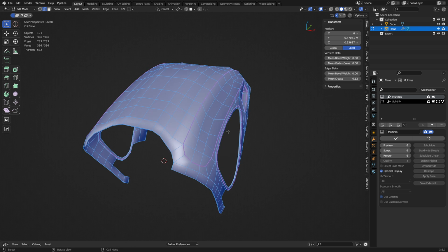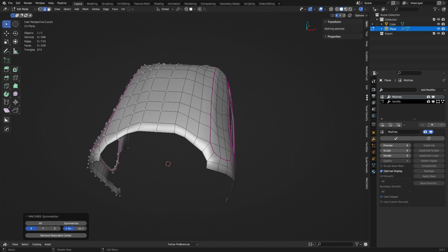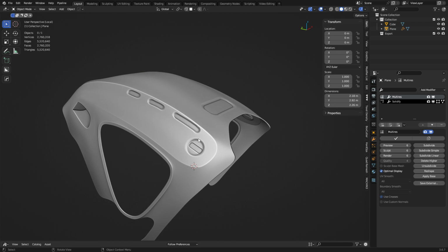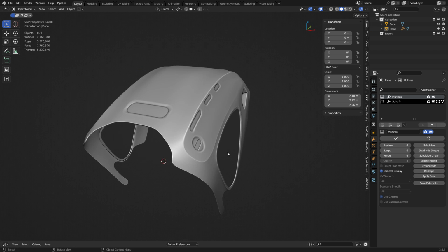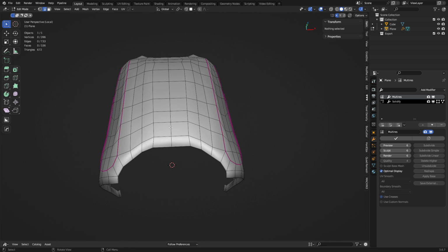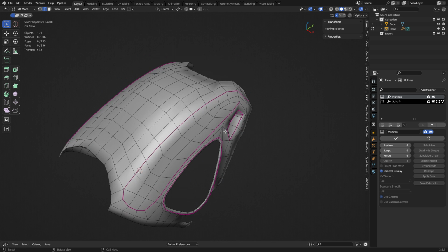You can take this mesh and you can symmetrize with Mesh Machine or use a mirror modifier possibly. Send it over, okay? And it will transfer the data to the other side as well. So you can still symmetrize, guys. It just has to be done very particularly. In a worst case scenario, you might get some weird hiccups here in the middle. Okay, so just keep that in mind.